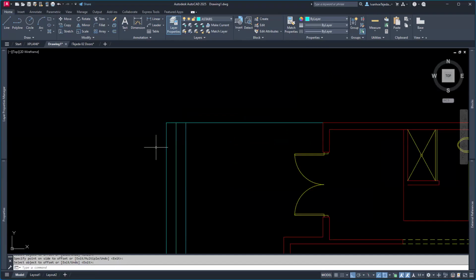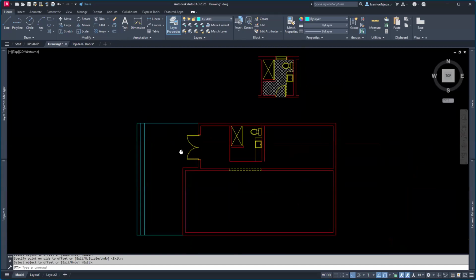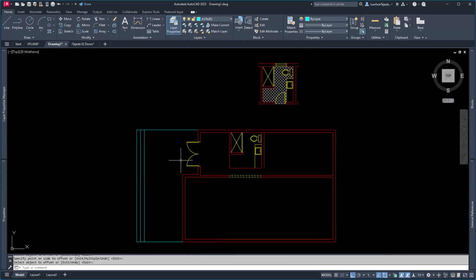So I start at 0, work my way up to 6 inches, take another step, work my way up to 12 inches, one last step, work my way up to 18 inches, which is 1 foot 6 off the ground. I'm all set. And then Control S, save, and continue drawing.